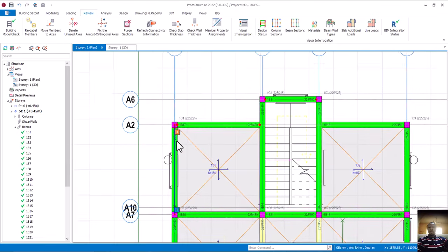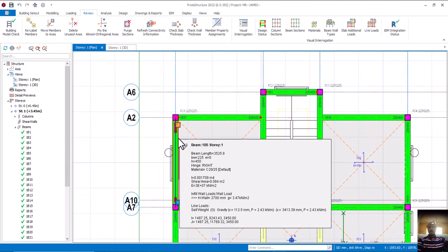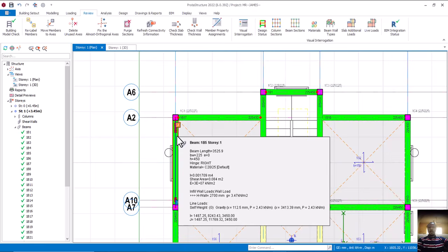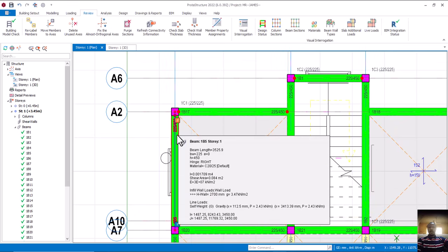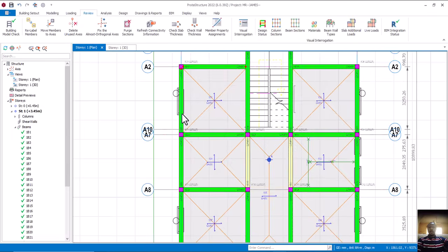So in this case, the amount of reinforcement is also reduced. Is that okay? Because if you don't hinge it, that means there's a moment, and there will be a need for what? For you to provide reinforcement to take care of that moment. Is that okay? That is fine.